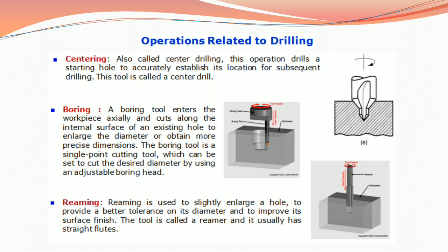Next one, boring. A boring tool enters the workpiece axially and cuts along the internal surface of an existing hole to enlarge the diameter or obtain more precise dimensions. The boring tool is a single point cutting tool, which can be set to cut the desired diameter by using an adjustable boring head.